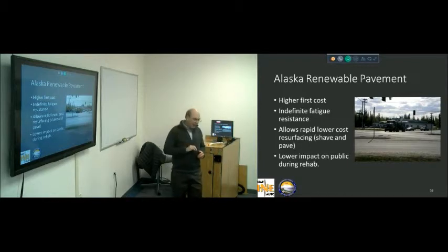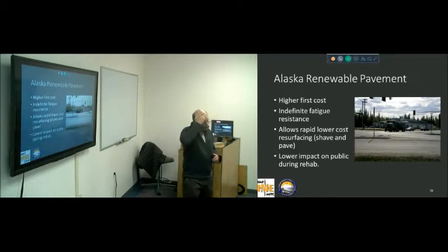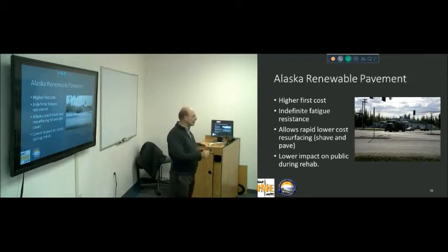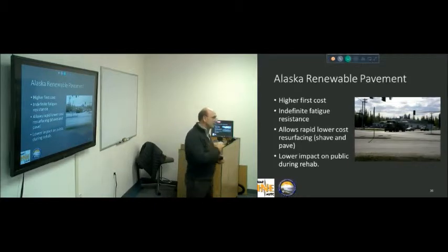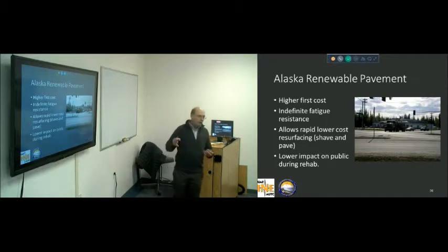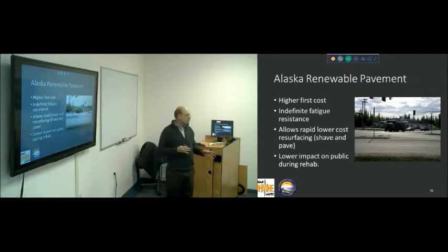And so the reason we like these, especially in urban areas, is because they have far less impact on the traffic. It is possible for us under Alaska Renewable Pavement to come in and replace a pavement literally overnight. We can mill it and pave it in one night if we schedule everything out. In many cases, what we do is we'll come in and we'll mill it, and then a day or so later we'll come in. The public is always on pavement. So it has minimal impact on businesses, has minimal impact on high traffic areas.